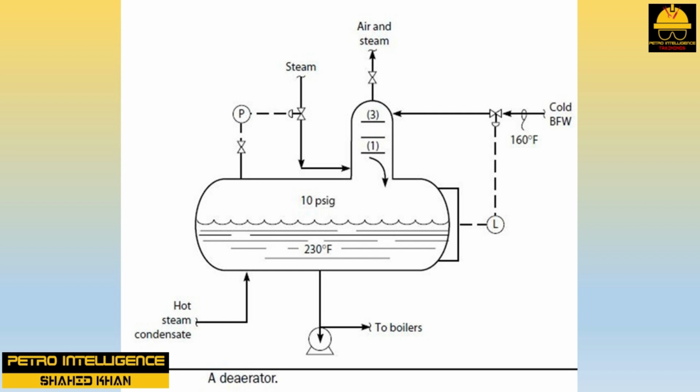Usually, heating river or well water above 130 degrees Fahrenheit would cause the laydown of hardness deposits inside the cooling water tubes, assuming the cooling water to be on the tube side. But using softened water as a cooling water supply permits that water to be easily heated to 160 degrees Fahrenheit without fear of precipitating hardness deposits. Thus, softened or demineralized cooling water can also be used as boiler feed water, and about 40% of the deaerator steam requirements are then saved.